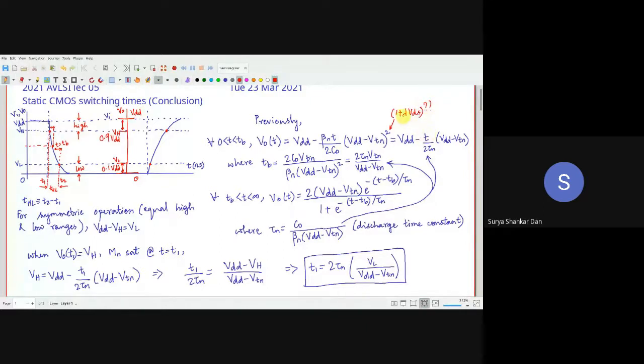है ना? Just see, this is the expression for the current in the saturation region. सैचुरेशन रीजन में तो 1 plus channel length modulation भी आएगा, है नहीं? Like I have shown you, this is only one. There are many other factors also which Cadence will take care of, or SPICE will take care of, the BSIM library will take care of, which we are not taking care of.